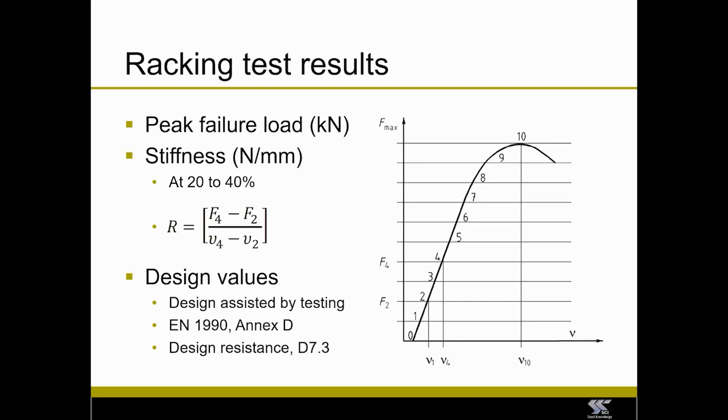So this shows an idealized plot that you might get from a test. In reality, you get a much longer tail to that test than is shown in that diagram, and it shows you how to calculate the stiffness. It's simply the slope of that output between the 20 and 40% applied load values.